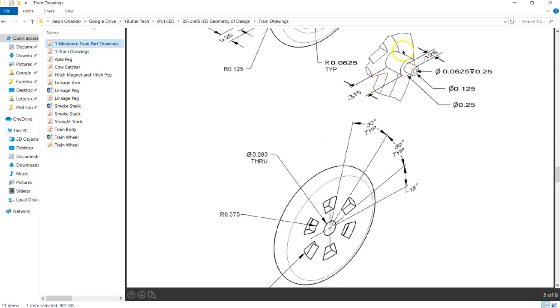This is a curved surface back here, so I'm not going to want to try to start on there. I actually want to start out here and then extrude back and basically tell Onshape to extrude to the next feature, and then it'll perfectly match up to that curved surface. So I need an offset plane that comes out this distance, this 0.375, to get my work plane, and then I will do this part back towards the wheel and then do this part back this way.